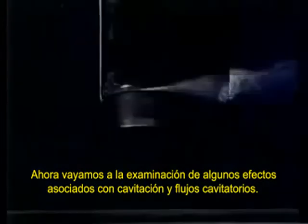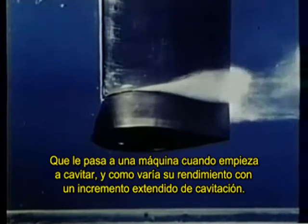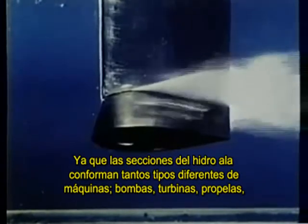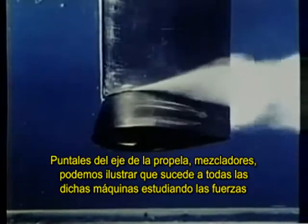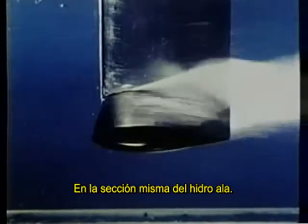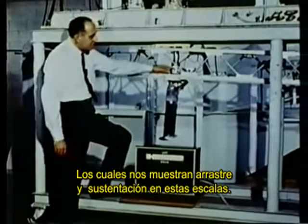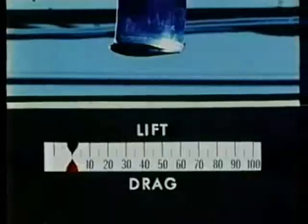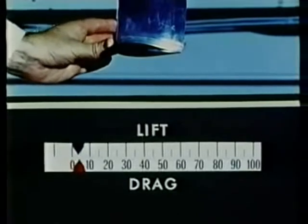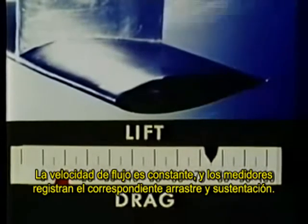Let's turn now to an examination of some of the effects associated with cavitation and cavitating flows. What happens to a machine when it begins to cavitate, and how does performance vary with increasing extent of cavitation? Since hydrofoil sections make up so many different types of machines, pumps, turbines, propellers, propeller shaft struts, mixers, we can illustrate what happens to all such machines by studying the forces on the hydrofoil section itself. We have suspended the first hydrofoil model from force gauges, which show us lift and drag on these scales. The flow speed is constant, and the gauges register the corresponding lift and drag.